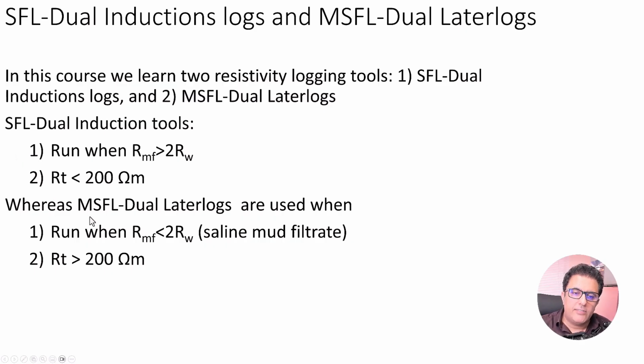And then we have another resistivity log, the MSFL Dual Laterolog, that is used for conductive drill mud. What I mean by conductive drill mud is that we make the drill mud from saline water or brine.